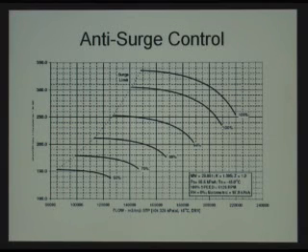And this is the flow that the compressor can go down to before the internal circulation of gas changes path and it actually tries to run forward instead of being compressed towards the back. So this is a very unstable range to be in. Usually when you surge a machine, it lets you know by having extremely high vibration, extremely high temperatures, and sometimes even higher noise levels than normal.